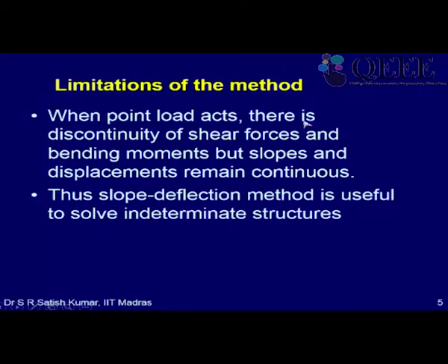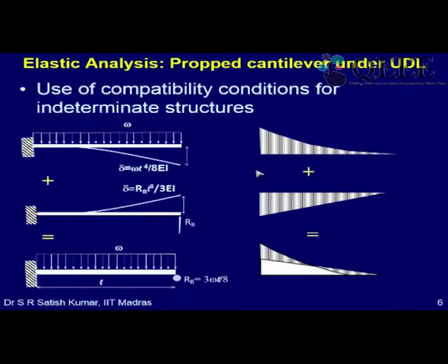So when a point load acts, there is discontinuity of shear force and bending moments, but slopes and displacements remain continuous. So that is the fundamental thing. The slope deflection method becomes useful to solve indeterminate structures. So that is how the different methods have evolved based on the convenience to apply them to a particular situation. Now here we are going to look at one such method which is very simple.